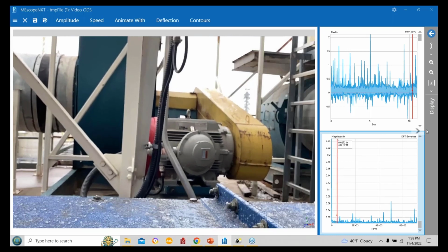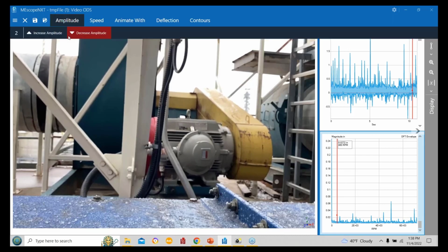This is an envelope plot down here, so it overlays everything. I just like to see the other peaks once in a while. So this, if I increase the amplitude a little bit, kind of a bounce there. I think it's the belt frequency. Belt frequencies typically come in multiples, so 2 times belt frequency, you get 2, 4, 6, 8, a whole string of them, and that might be what's littering my band down here, the noise floor.